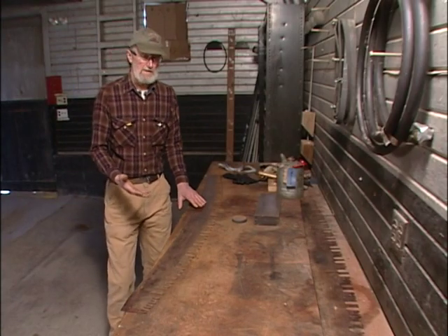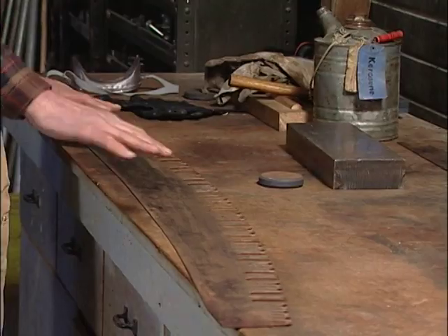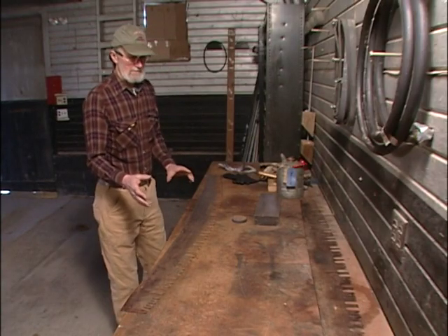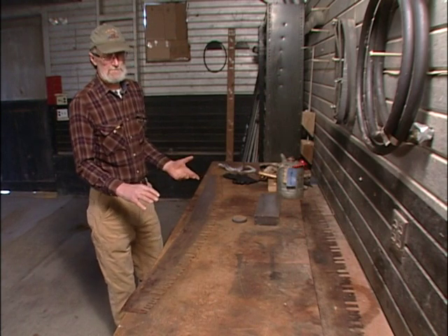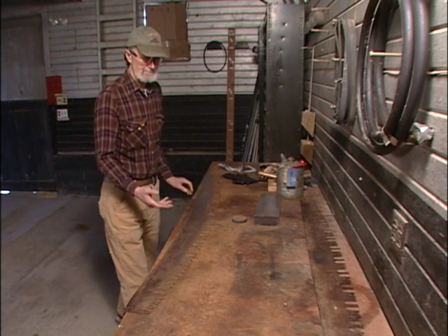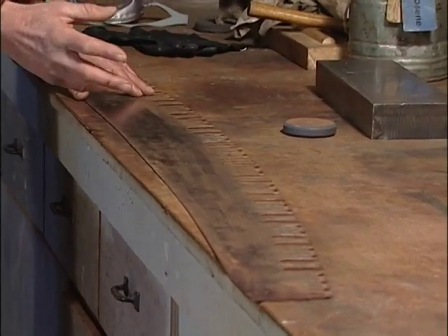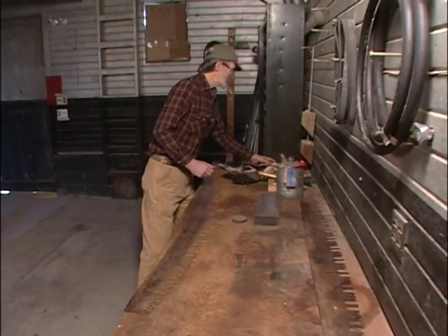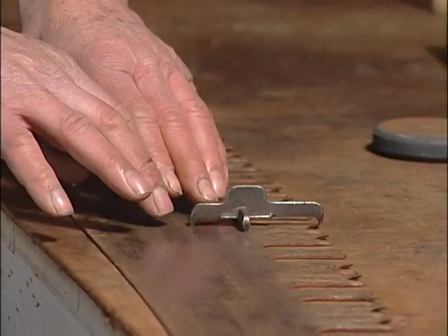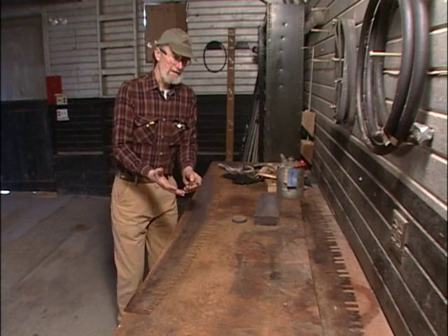You need to have a clean saw for a number of different reasons. One of the primary reasons is that when you're running your tools over the saw, the rust on it is pretty abrasive. And if you don't take the rust off of it, you'll wear your tools out pretty rapidly. A saw that has rust and pitch on it will tend to bind in the kerf. Another reason that you want a clean surface, a flat surface, is that when you're using the spider on the saw, which is a tool that looks like this, if you have bits of dirt and pitch on there, it'll end up resulting in having a mismeasurement of your set.